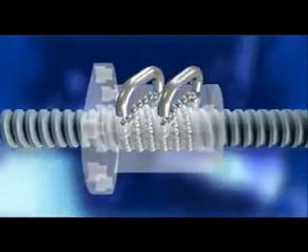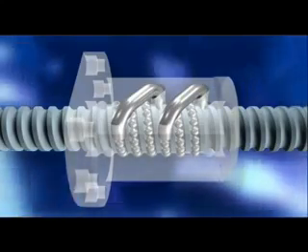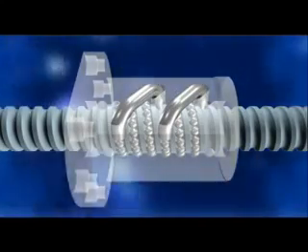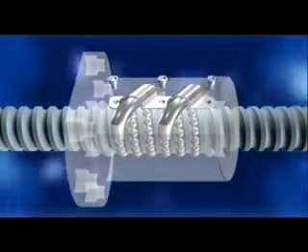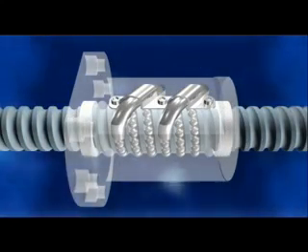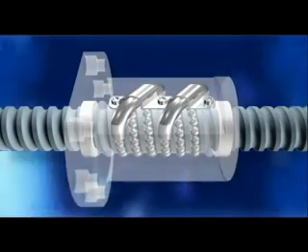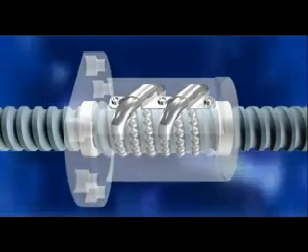Return tube. The bearings return via the return tube, which ensures that the bearings travel along a sealed circuit. The fixture block is used to anchor the elbows. Wipers. The wipers are located at the outer ends of the nuts and serve to ensure a good seal. They prevent dust and cuttings from entering the bearing circuit.